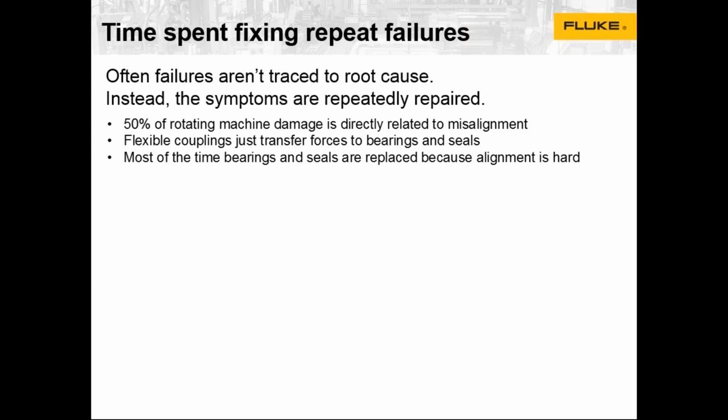The root cause is imbalance and misalignment. So if we ignore imbalance and misalignment, we're just going to keep replacing bearings again and again. When I was in the Navy as an electrician, we would replace the bearings on the motor, the mechanics replaced the bearings in the pump, and then a year later, we were doing it all over again.